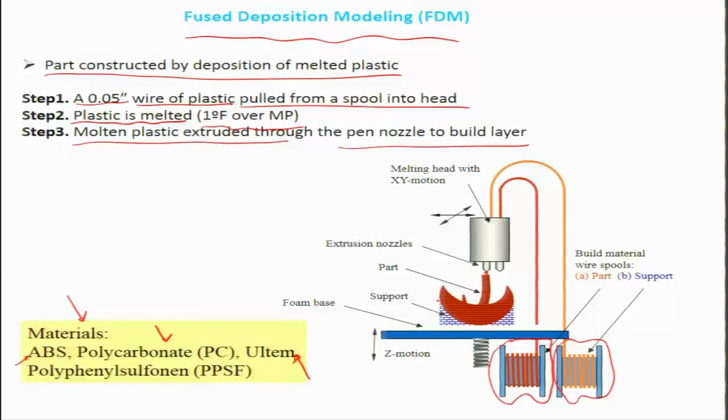If I look closely at how this part is being shaped, you can see the support material right here in blue and the base material for the part, which otherwise could not have been created in 3D space had the support not existed. The support is very low in printing density. It is just like legs for a structure so that it can stabilize while the build up is happening.